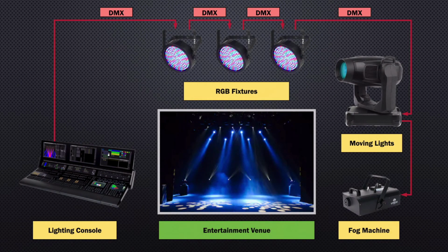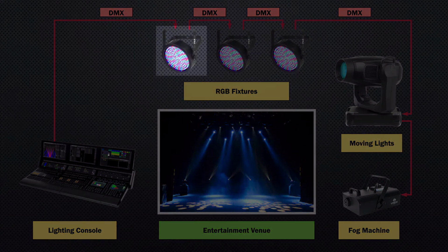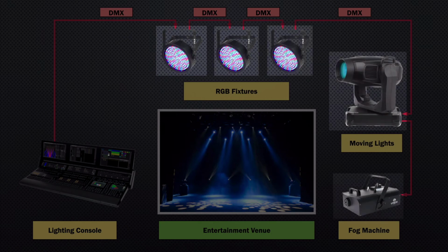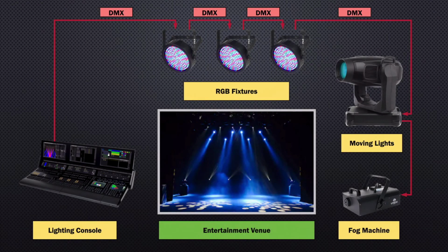The DMX signal is then transmitted over an XLR cable and connected to a DMX-capable lighting fixture. Another XLR cable is used to connect that fixture to the next fixture, then the next, etc. In other words, the DMX control signal is daisy-chained to multiple fixtures in the venue.